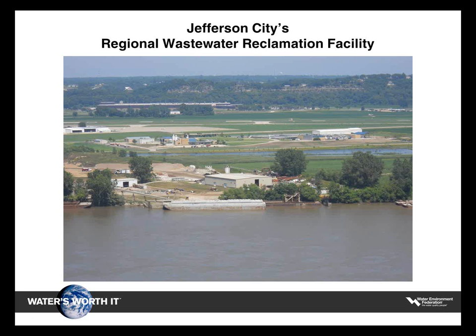Our SBR has a design flow of 11 MGD and a peak flow of 60 MGD. Our permit limits are 30 for BOD and suspended solids, and we have an E. coli limit here: 1,030 per 100 mL on a weekly average and 206 on a monthly average. And our current flow is about 8 MGD.